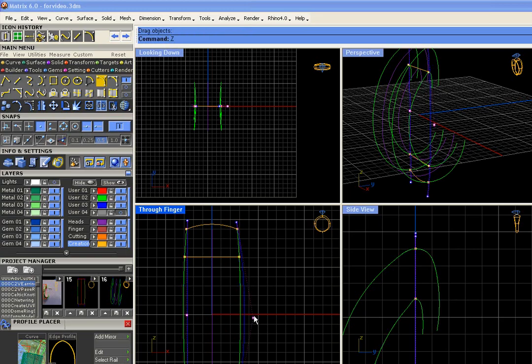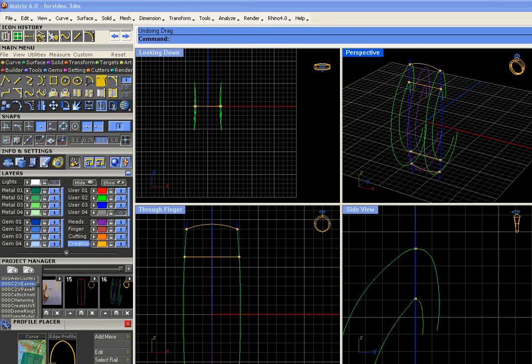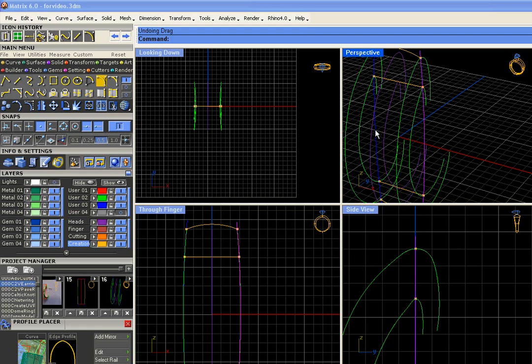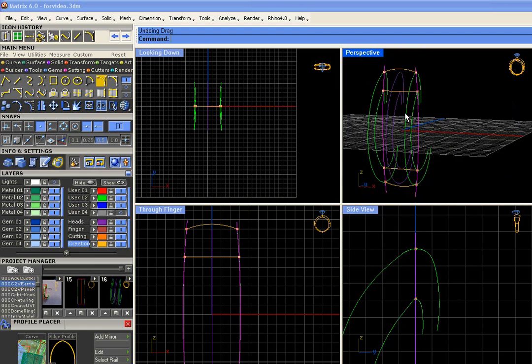Okay, and just to check that these are the new ones and not the old ones, we can select their control points and drag on them and just see that the curves won't change, okay? Because remember, we got history turned on and we ran curve from two views and everything. So these are the new ones, okay? And these are okay to split. The old ones are not okay to split.